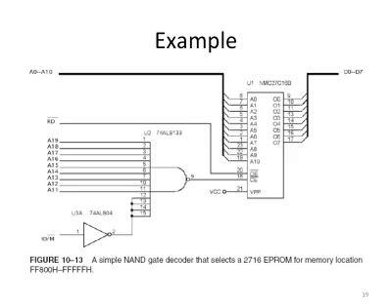And for other addresses on the upper 9 bits, it will cause this NAND gate to output a 1, because if any of these 9 bits is 0, this NAND gate will output a 1. And in that case, this chip will not work. So the output will be put into high impedance. Essentially, the microprocessor will see nothing on the data bus. There will be no valid data on the data bus.